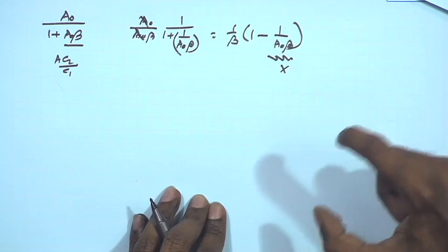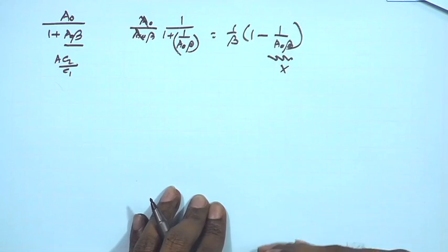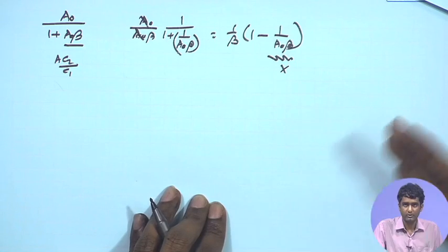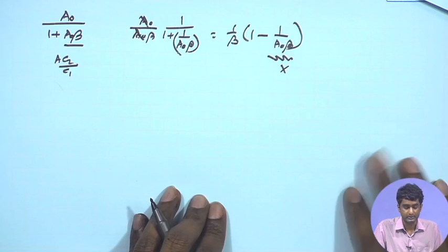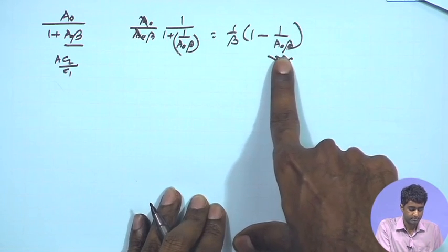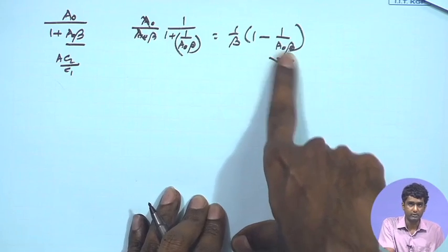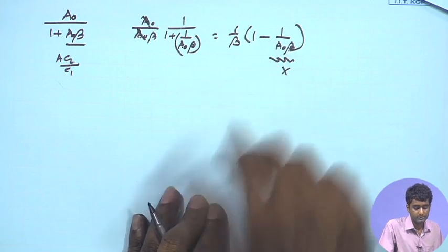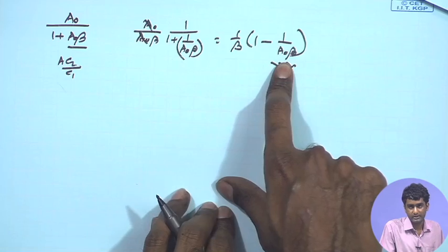So, you want to record data with 100 levels of precision. Therefore, you do not want even 1% of corruption in the data, otherwise the 7th or even higher number of bits in the data is meaningless. So, in order to have 1% precision or close to 7-bit accuracy, I would like this quantity to be sufficiently higher than 100, at least around 100.